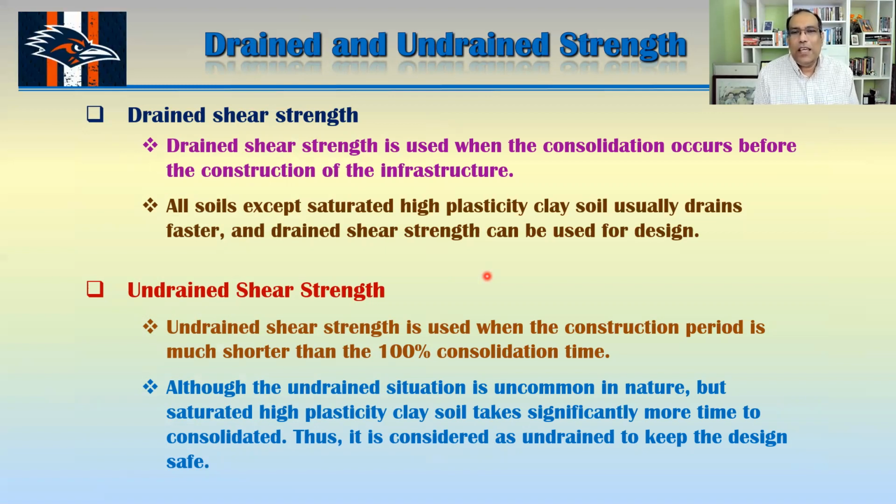If your construction time is more than the time required for consolidation, then basically you can use drained shear strength, because the drained shear strength is higher in most cases. In some cases it may not be higher, I'll talk about that in future. But in most cases, you can use it for design if the soil will be consolidated before the construction.